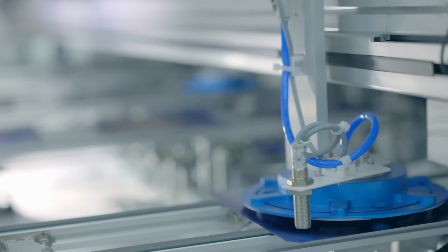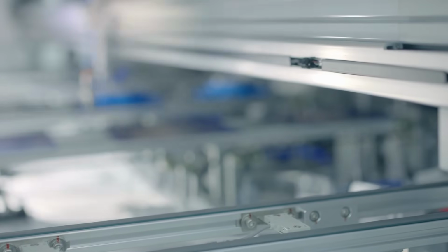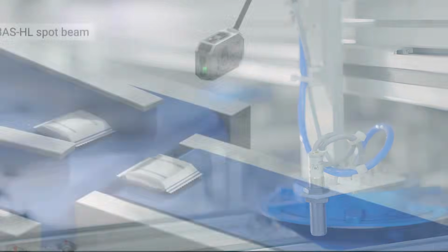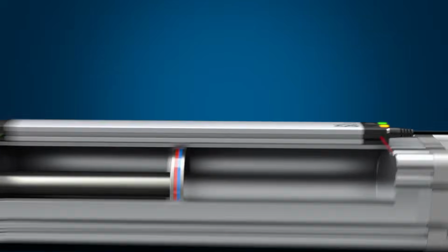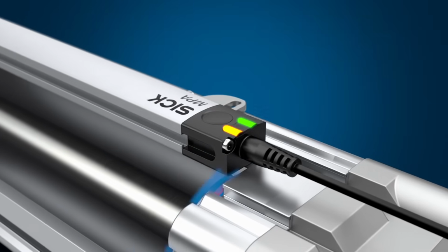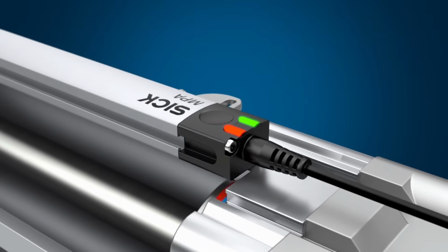Now, why do we need digital output sensors? In many applications, we don't want to measure how much something is. We just want to know whether it's there or not. For example, in part detection, we just want to confirm if the part is there. In counting applications, we just need a pulse for each item. In position confirmation, we just need to know if the position is reached or not. In all these cases, we just want yes or no, on or off information.